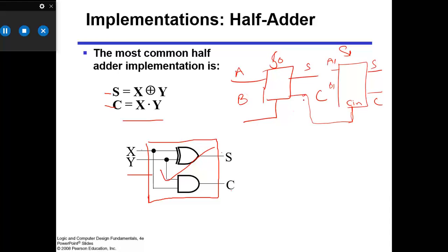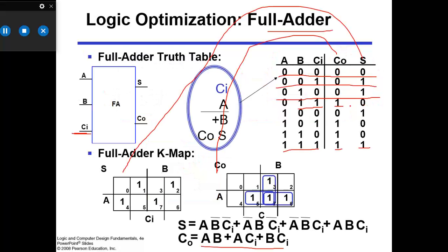So a half adder can be used at the zeroth bit of an adder, but there must be a full adder, an adder with 3 inputs, A, B, and a carry in input, to proceed for advanced addition. A full adder, as compared to a half adder, has a third input Ci, which takes the carry input generated from the previous bit. Then we can simplify this with a truth table, make the truth table according to this K-map, and then solve and simplify our circuit for the final equation.